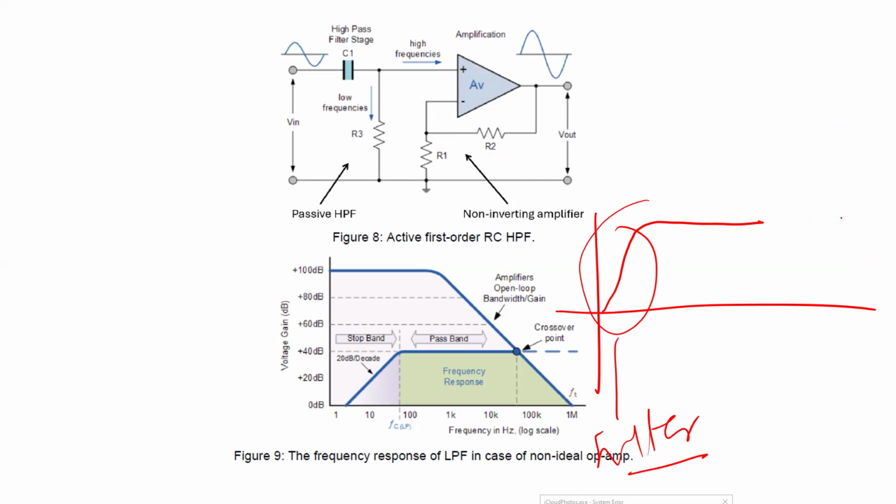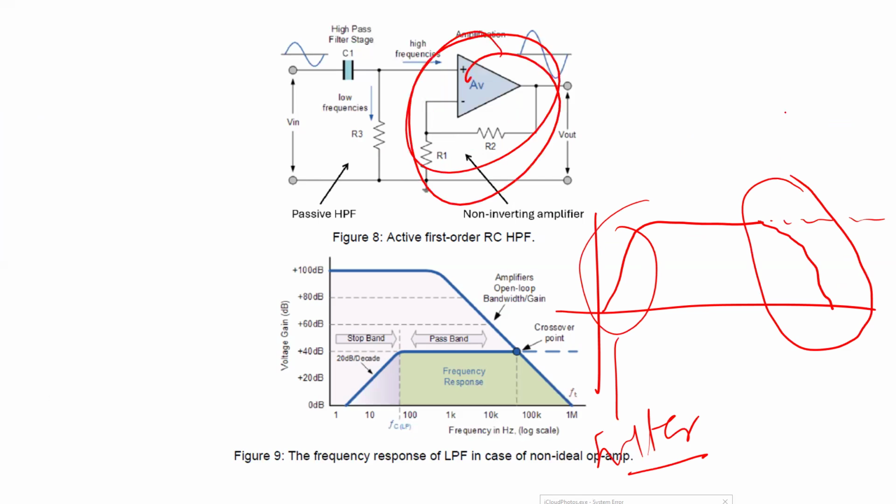However, it has to go all the way to infinity. It's not going to happen. I will see now something like this will happen here. Okay, is that a filter? No, it's not. Yeah, you can see it like a filter, but I didn't put it. But this is mainly because the op amp itself is not ideal, and it's not going to work at very high frequencies.